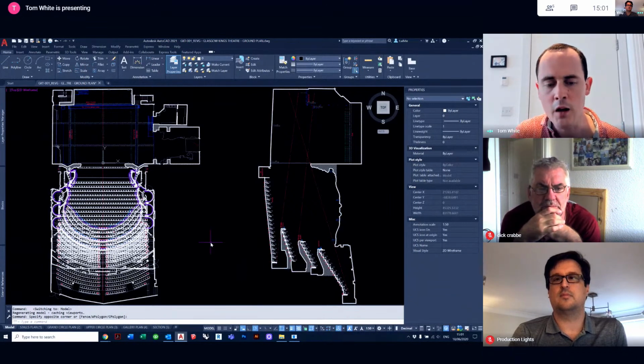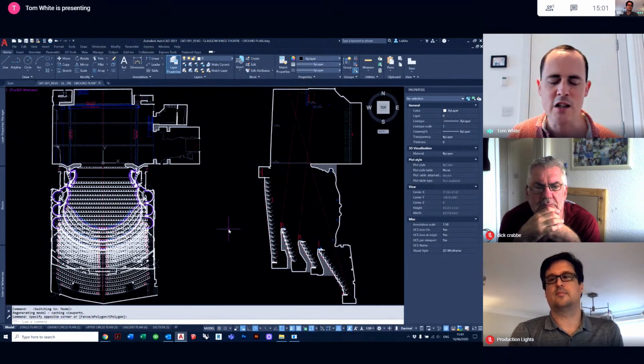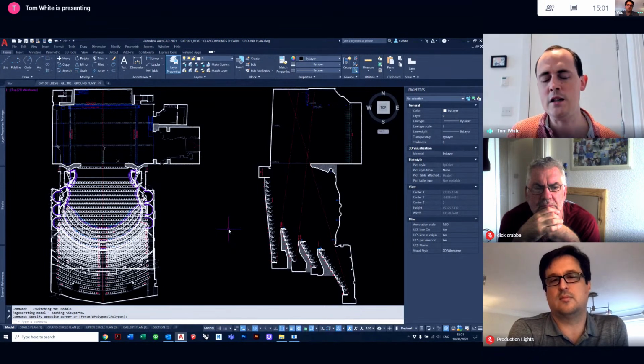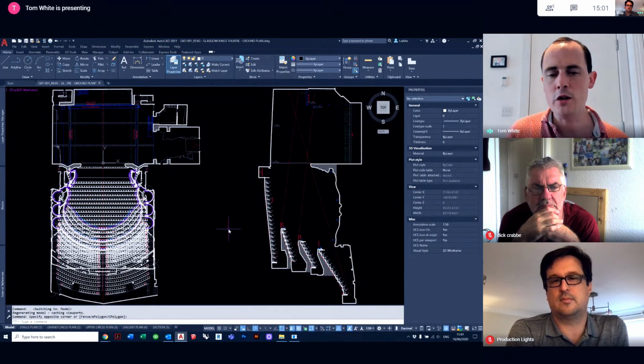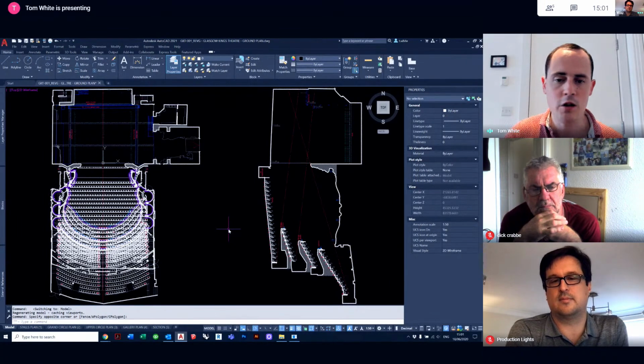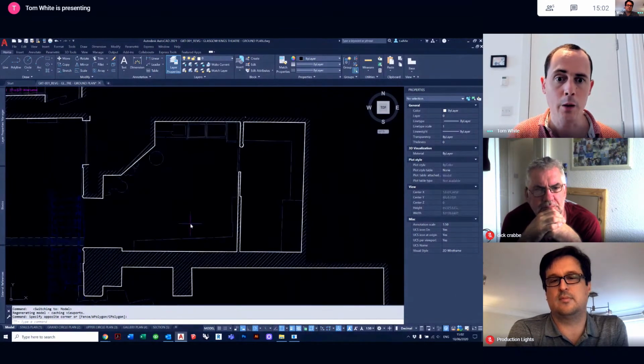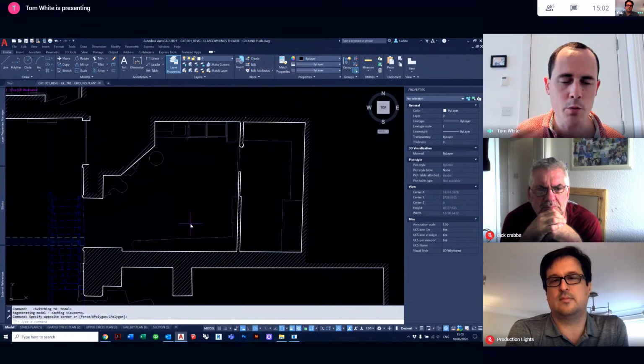Often, and I think we've talked about this over the last few weeks, there are variations, but more often than not you do drawing in model space, and you do printing or the layout in paper space or layout space. Because you're able to draw in model space, you can plot or print from model space if you so desire. Just as an example, this is a theatre, and we're going to zoom into this corner up here, which is a back of house space that somebody needs a print of. So if you desire, you're very welcome to print.